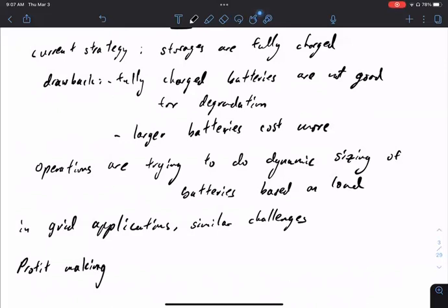If you work for City Light, for example, in the battery or smart grid group, you think about this all the time. You send surveys to people. You look at each load in each area and figure out who's the fire station, who's the hospital, and so on, to make sure you don't cut them. For residential areas, you do a lot of surveys and look at who's the important load. That's why a lot of monitoring goes on. Any other questions about that?